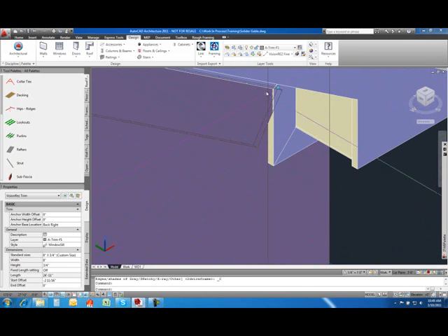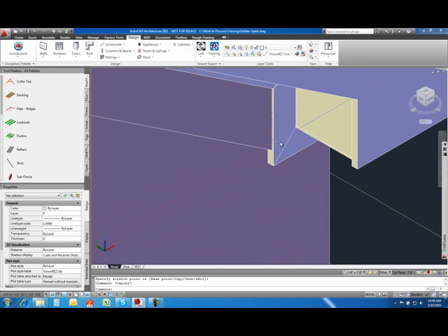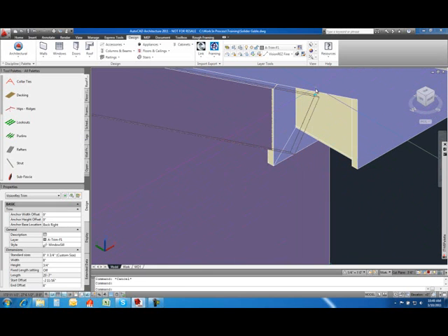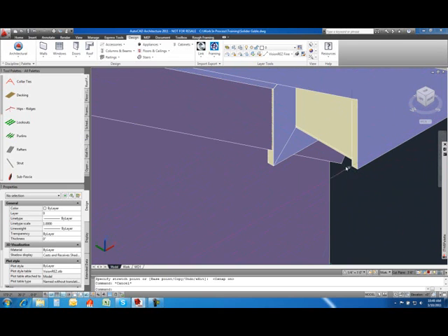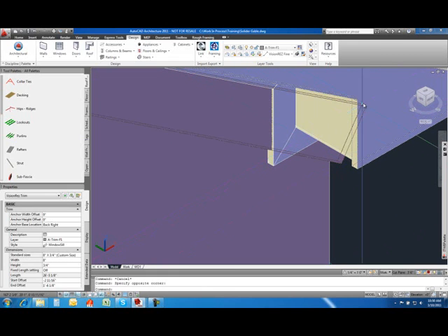If we're doing construction documents and we just want that to generate nicely, all we need to do is stretch that trim piece so that it goes beyond the frieze board, and so we don't actually see it, but not too long. If we make it too long, we'll actually see it beyond where we actually want to see it. So it gets beyond that frieze board. So that's a little too long, so we can actually drag that back.